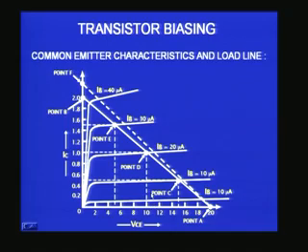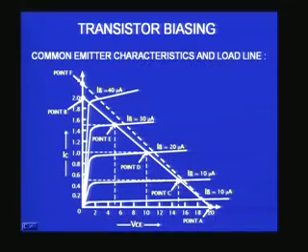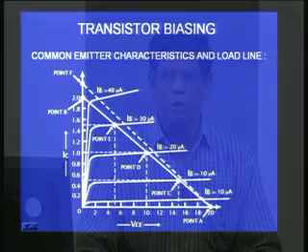And therefore if you want to use a transistor as an amplifier, then you must confine yourself to the active region, which is the region generally in between these two. So we can see that only the point C or D or E, or something in between, can be used as our operating point or Q point.